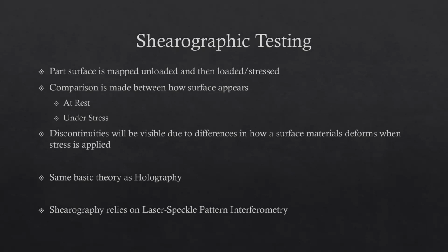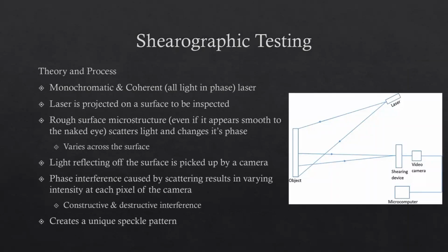But now what happens, again, discontinuities will become visible based on how material deforms when the stress is applied. And it uses that same basic theory, the same basic fact that light acting as a wave is going to have constructive and destructive interference. And what we use is something called laser speckle pattern interferometry. A long way of saying it. And so now, instead of splitting our beam, okay,